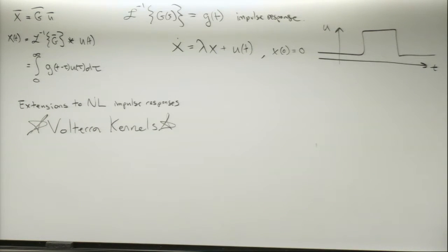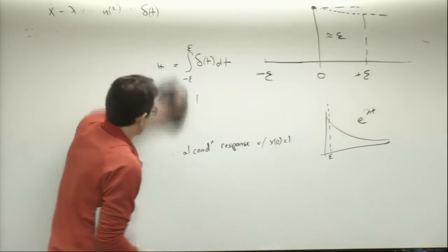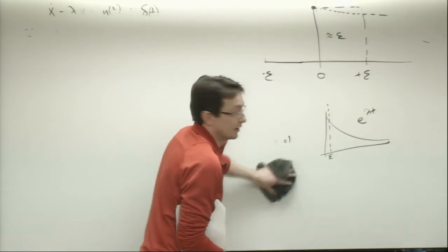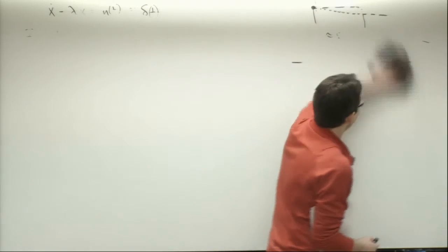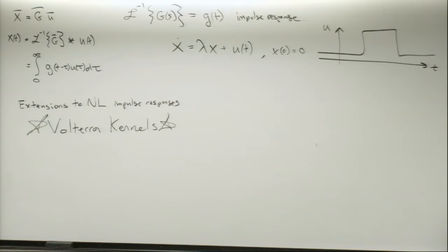So how many of you have seen the convolution integral illustrated in a movie? Good, you're about to. Okay, so we're going to write a script in Matlab that's essentially going to go through and compute the convolution integral as tau goes through the system, as t goes through the system. And we're going to figure out exactly what this input does and exactly what convolution means kind of intuitively. Okay, so we have our input.